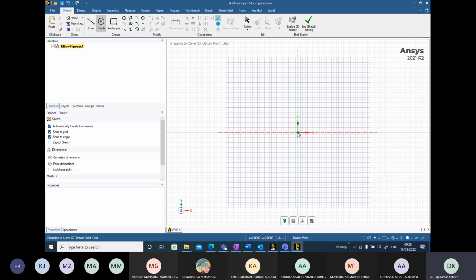It is a hollow pipe. I create the outer circle. Left click, it selects the center of the circle. I extend it, and when I extend it, you can see the diameter of the circle is highlighted as 22.8. Don't left click. What I'm going to do is type in the value of the diameter I want. So let's say I want 20 millimeters. That is the diameter I want, and press enter. Okay, so the circle is created with 20 mm diameter.